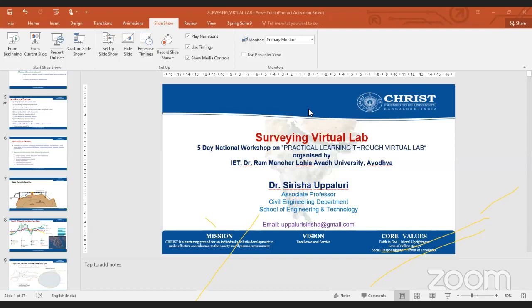We don't know about MSL over there. In reciprocal leveling there is no need of MSL. See, MSL we are going to have at one position only, the benchmark. That benchmark is given at A. Yes or not? The benchmark is written over here. It is 250.0 meters. Yes or not? So I'm going to fix the instrument at a convenient position to take the backsight first.